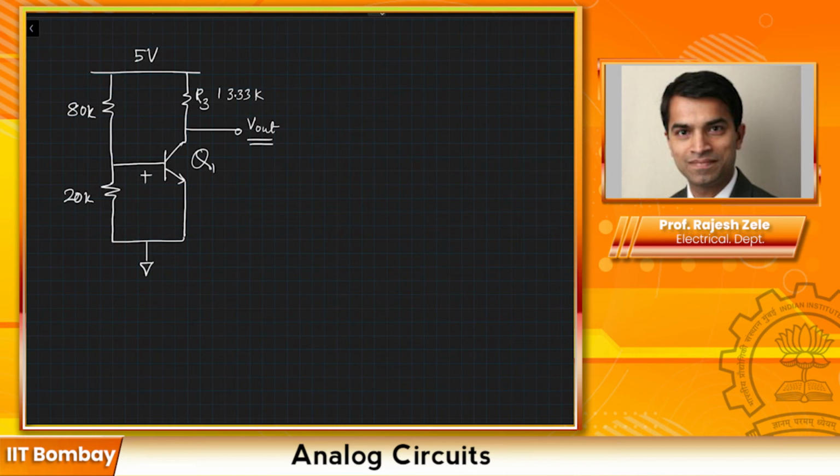We know that VBE will be equal to 0.7 because the transistor base-emitter junction is forward biased. We go back to the same method again, step by step. This is our Thevenin equivalent of 1 volt and this is our 16K. We are back to the DC operating point, so we are doing DC analysis, or a large signal analysis, right now.